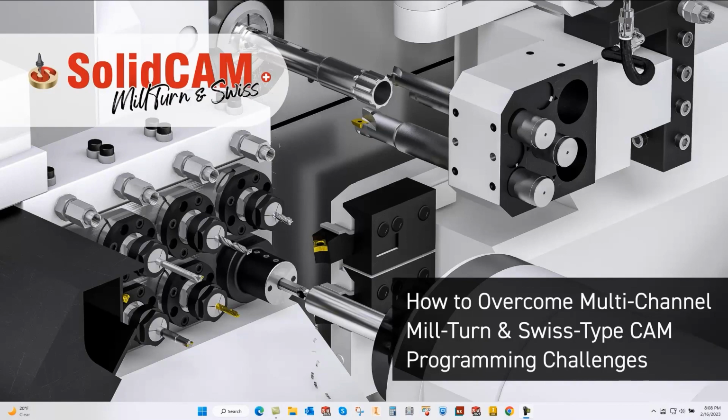Now that's a really good question, because you have G-code simulators. They require a reverse post in order to work, and that simulation from the G-code is only as good as the reverse post that's interpreting the G-code to the machine simulation. We have a similar situation in here. We're going off of the apt.cl file, but our simulation is going to be based off of that, but it's also going to be based off of how good our MCOs are and the post. So there's always an intermediate process in between, and that is what makes either G-code or apt.cl verification good.